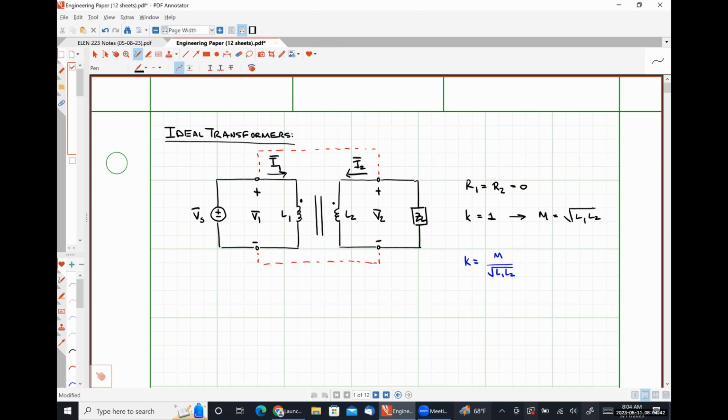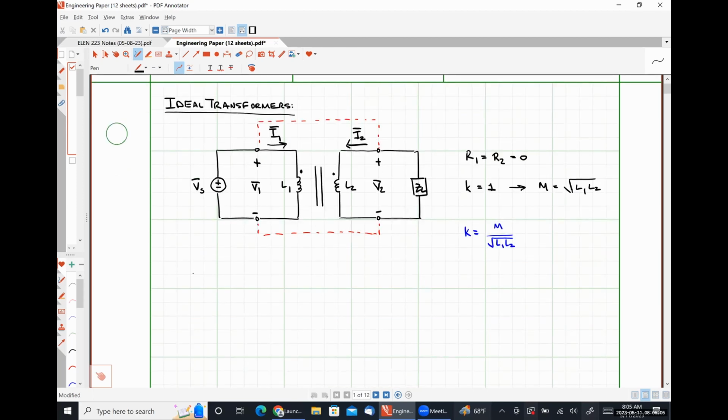The inductance of a solenoidal coil, we talked about this, I think, 3 class meetings ago, is proportional to the number of turns in the coil. So we could say that L1 is going to be equal to some constant value K times N1 squared. And similarly, L2 would be K times N2 squared, where the value of K here isn't particularly important. It's just glossing over the electromagnetic relationships that we're not really concerned about right here.